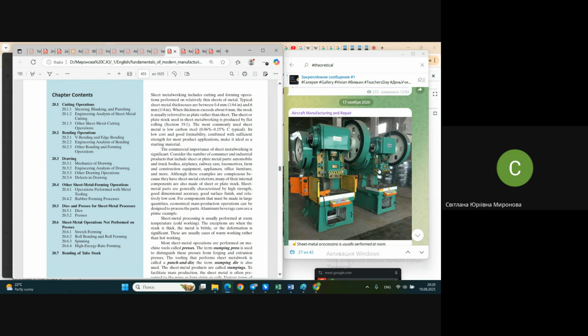It's the speed of applying force, the external speed. It's not the speed of deformation. It's the speed of deforming force application, let's say. This external velocity is in the range of 12-15 meters per second. Such a press, even the slow ones, is able to make 40 strokes per minute, up to 150 and more strokes per minute. Practically, they are shooting like a machine gun.